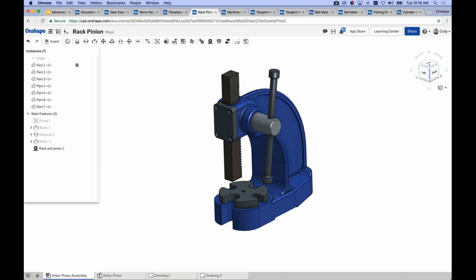Now, one thing I want to mention just briefly here is that in all of these examples, I've chosen 1 mate and 1 mate. But just realize that's going to be the most common scenario, but you can use other things. One good example of this would be a screw relation, where I may have both degrees of freedom in 1 single mate. That is acceptable.